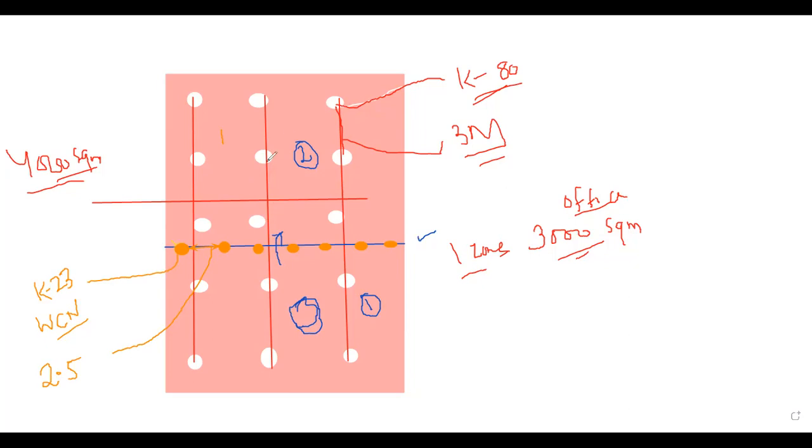So how will it operate? Already we have a sprinkler. For example, fire happened here, this sprinkler will activate. So how will this water curtain operate? Through the flow switch, the panel will read it. Here we have a flow switch. Generally, we can take two zones, with two pipings if you want. This piping we will do for this zone, and another piping for this one.